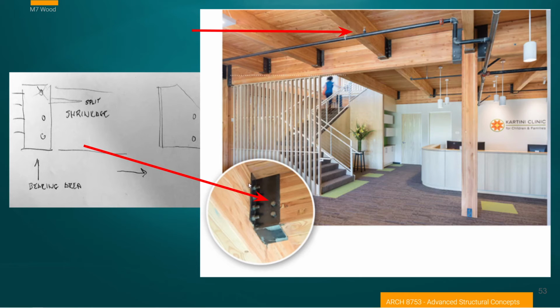of these details and I was wondering why these bolt systems were the way they were. And I think one of the reasons is that these laminated timbers will shrink. And by providing too many, in this case, the weight of this beam is being carried on the bottom plate here.